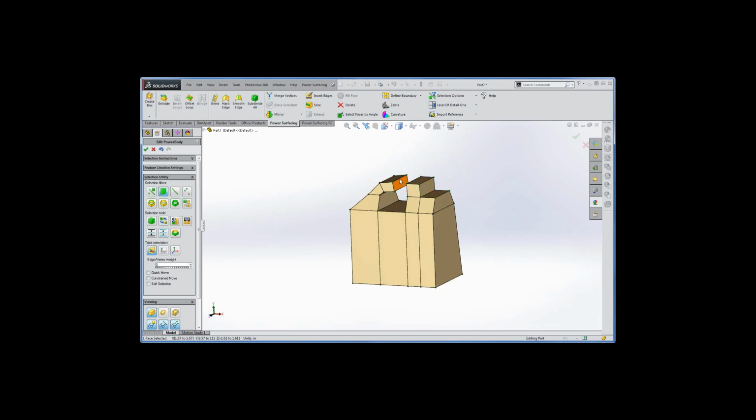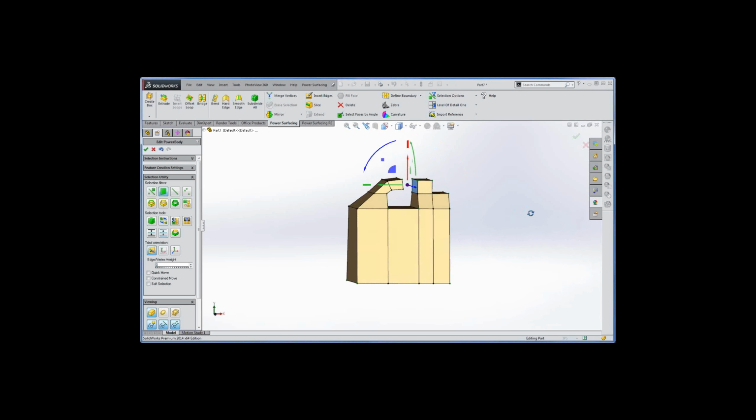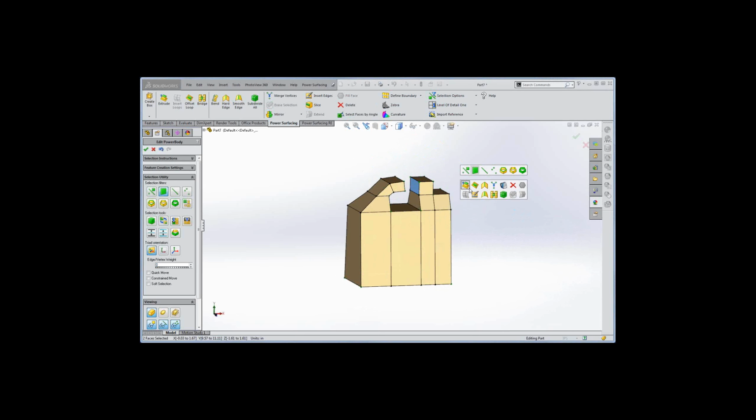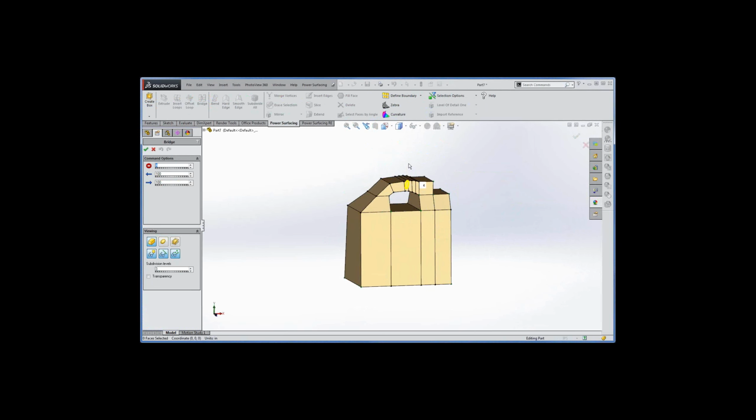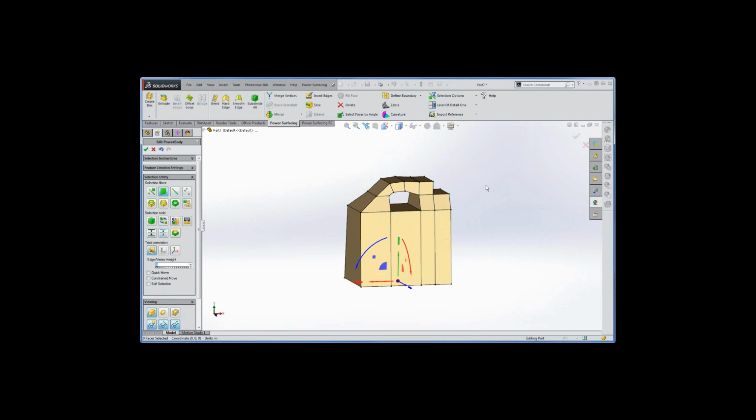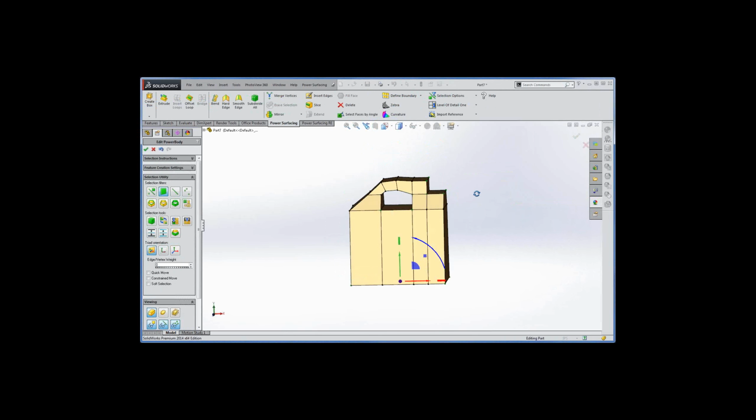And that's because we have a lot of tools to help you with your modeling, and one of them is the bridge tool. And once again, I usually access it from the right-click menu. So I click on my bridge tool. I've got an option to add more loops, segments if I want, but I'm going to leave it at 1 and right-click to finish the command.